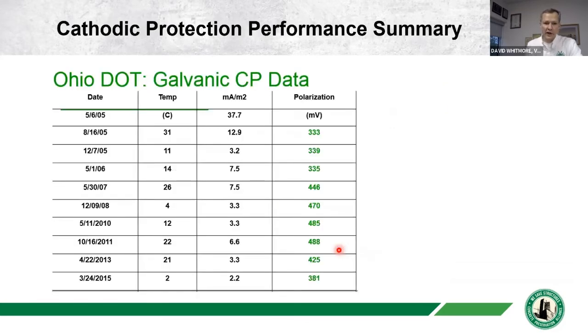And in answer to your question, or the person, whoever was asking the question, this system was designed for galvanic cathodic protection to meet the standards here, which are pretty similar to what they are in Australia. 100 millivolt polarization is the minimum required under the NACE standard. And it has consistently been over 100 millivolts of polarization throughout the entire protected area for, well, it's 10 years of data shown in this slide, but we have 15 years of data.